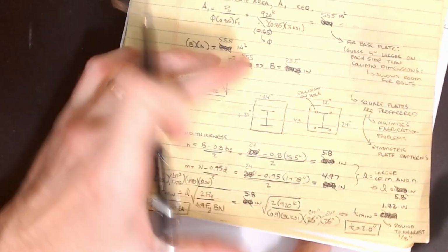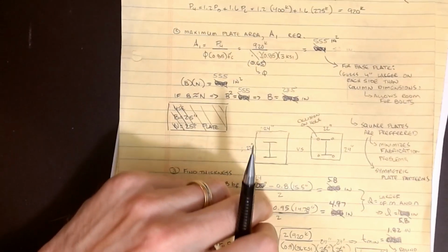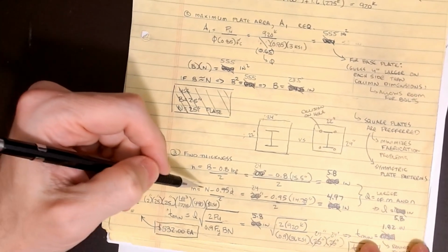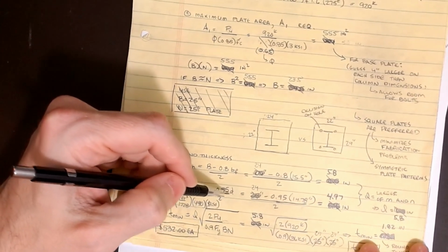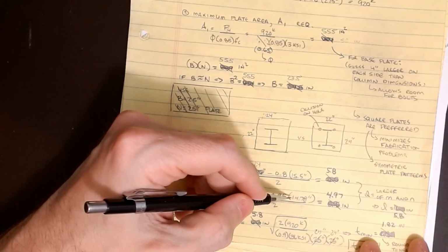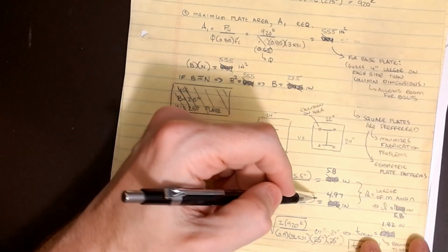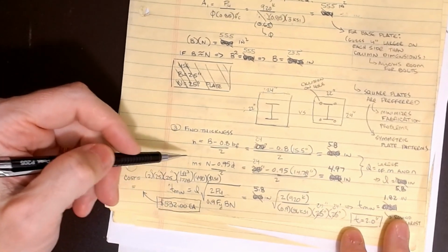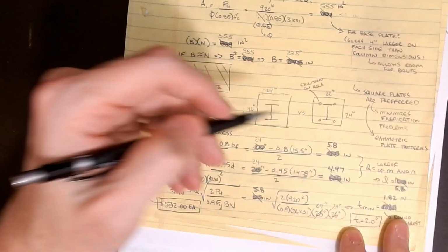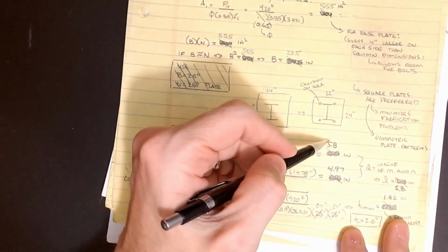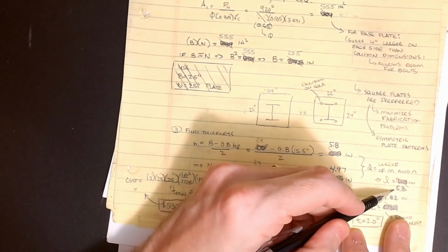Okay, I'm getting a little bit of glare on this. There we go. That'll help. Okay, and then my little m is going to be (big N minus 0.95 d) over 2. Okay, and so that's 24 minus 0.95 times 14.78, divided by 2. I get a 4.97. Okay, and so to size for the flexural case, we're going to choose the larger of these two values, the larger of m and n. So my L parameter is going to be the larger of these. It will be 5.8 inches.